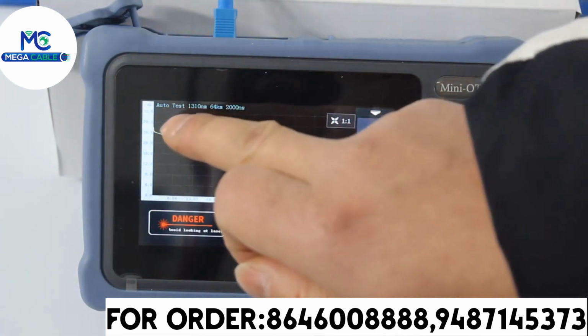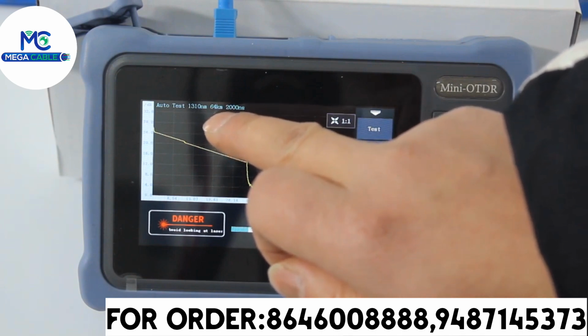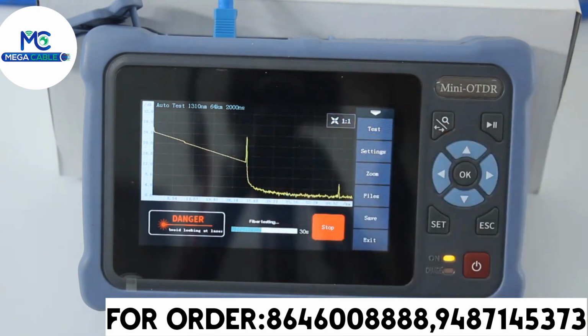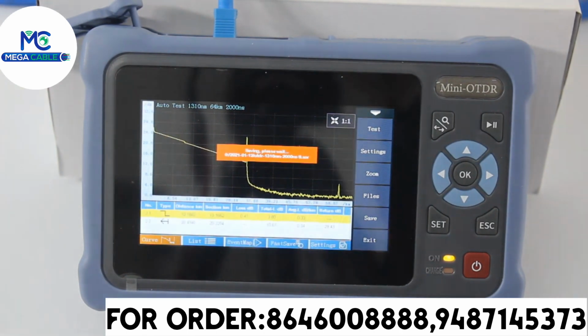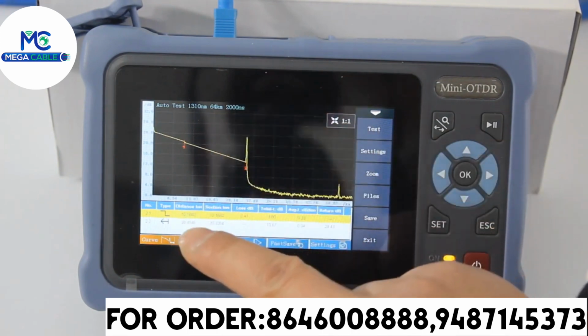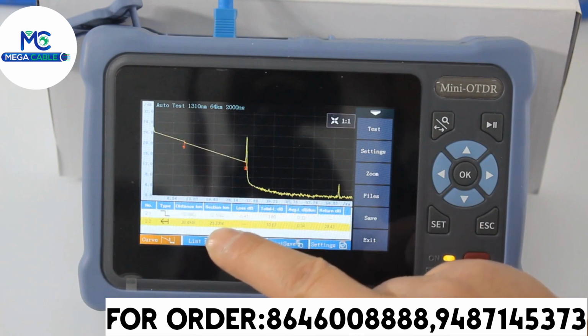On screen it shows auto test, wavelength 1310 nanometer, measurement range 64 kilometers, pulse width 2000 nanoseconds. It is autosave. This is the curve. There are two events. The first event is about 10 km. The second event is about 20 km.